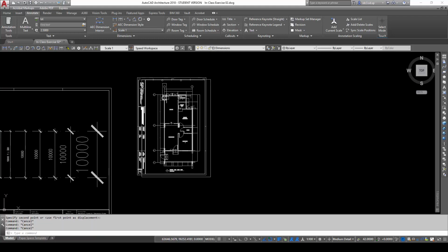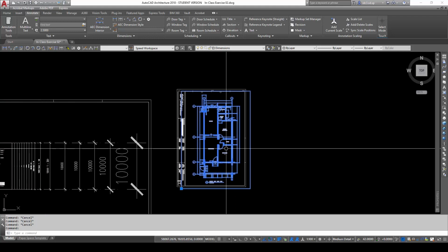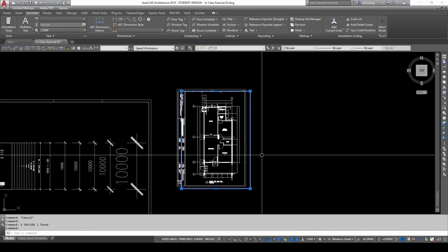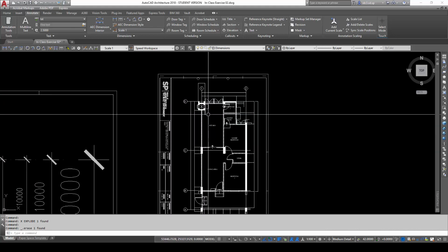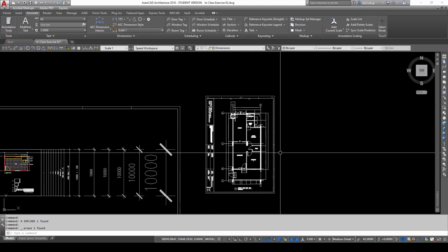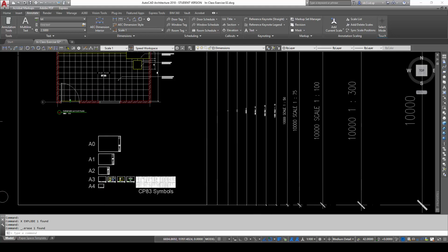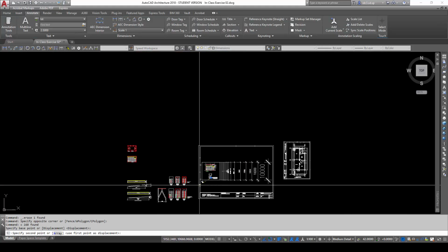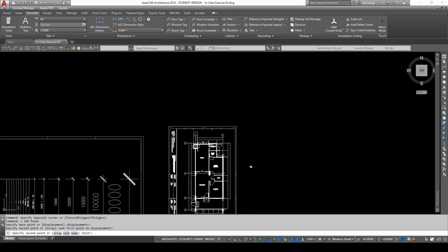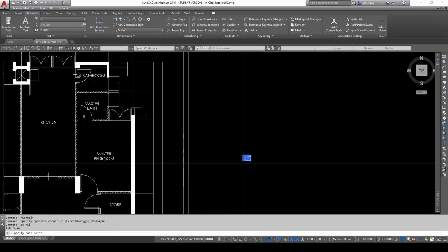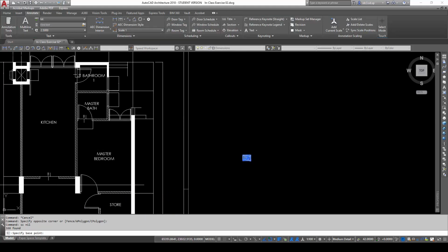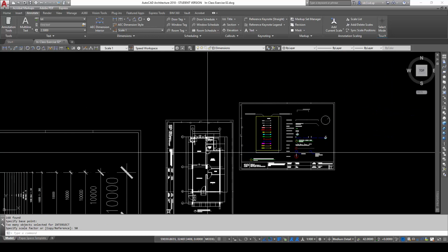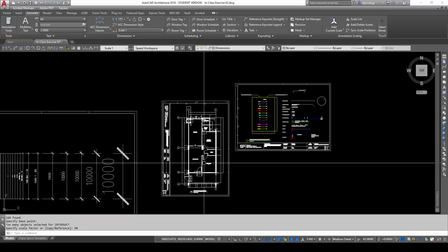like that. Okay. And because we inserted this drawing as a block, we will need to explode it by typing in X space, and we would have the drawing fitting inside this title block already. Okay, so the next thing we are going to do is make a copy of the template symbols and scale it up to the target scale that we want to plot this one at, 50 scale. All right, and then we can begin to do our cleaning up work and necessary processing, etc.